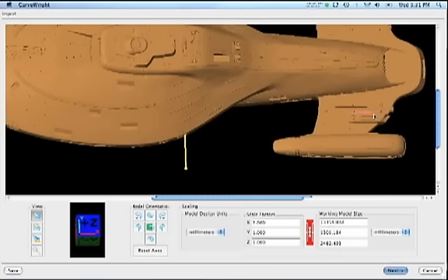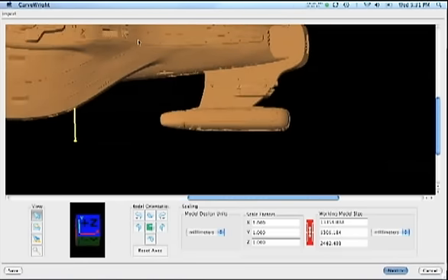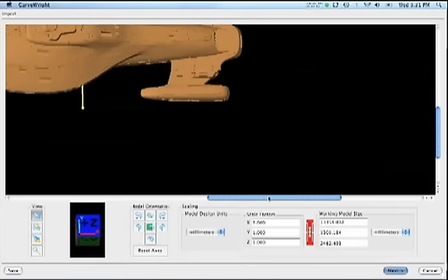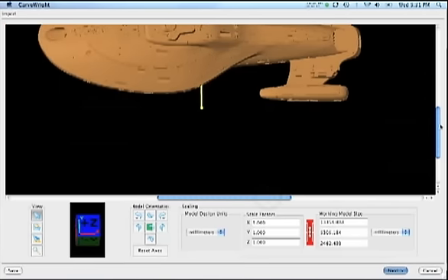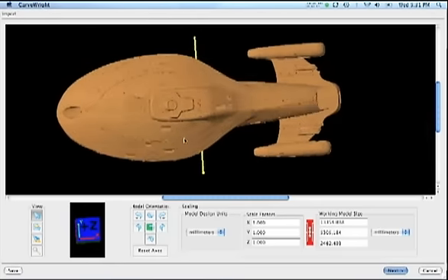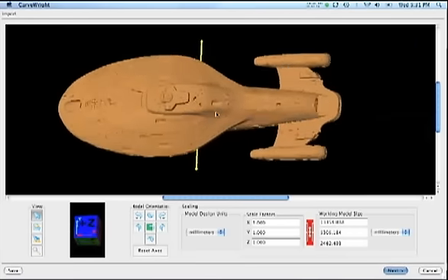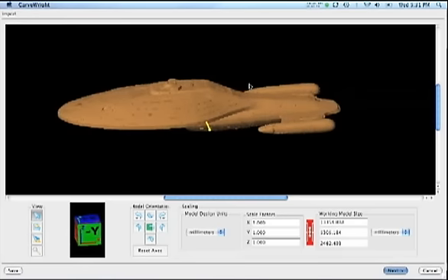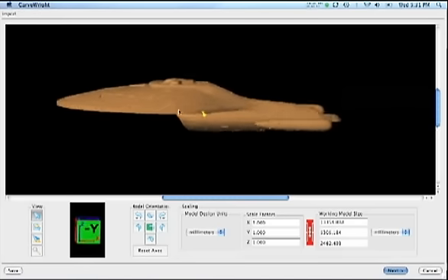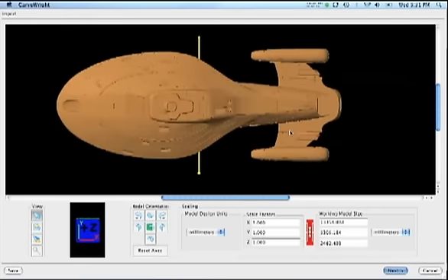Alright, when you're inspecting it here, you can look for errors in the STL. Any of these little pink areas that you're seeing are problems with the STL, which can cause you problems, and in most cases are going to make a model invalid for slicing and carving. After playing with this model for a while, I've found ways to work around that on this one. We'll have to do a little bit of cleanup in our pattern editor, but we'll get this one actually ready to carve.